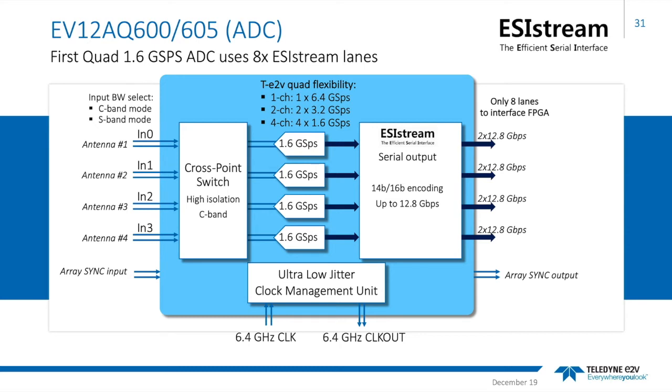It's a high-end wideband device. Signal inputs are applied on the left-hand side and flow into a broadband cross-point switch, featuring a full power bandwidth of 6.5 GHz typically. This switch gives the product considerable flexibility. For instance, it allows the individual inputs to be interleaved, enabling single, dual or quad channel operation.